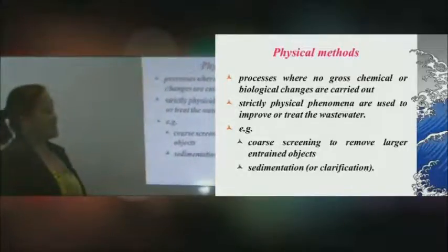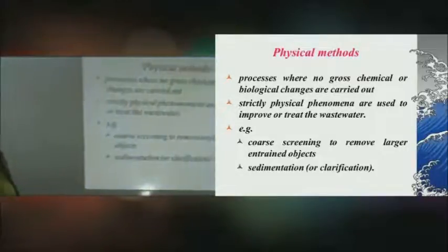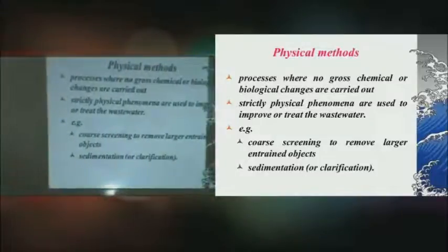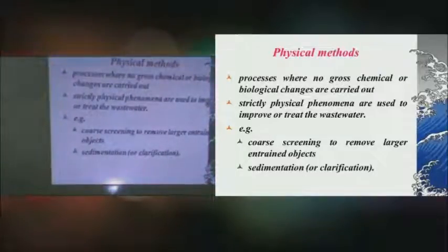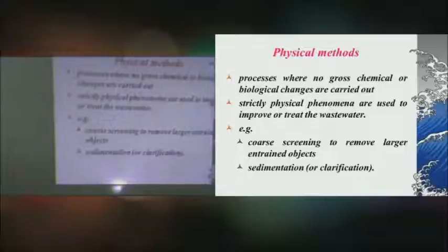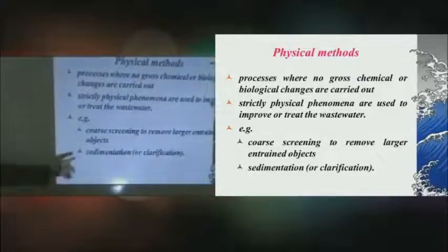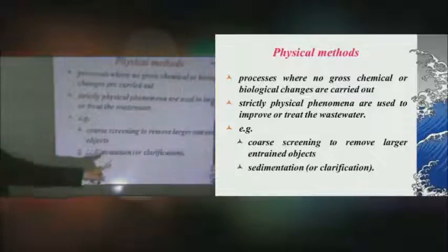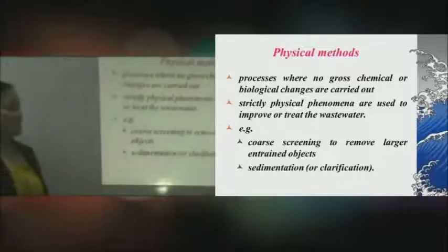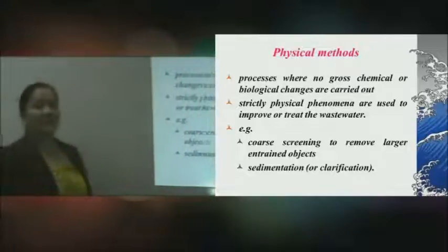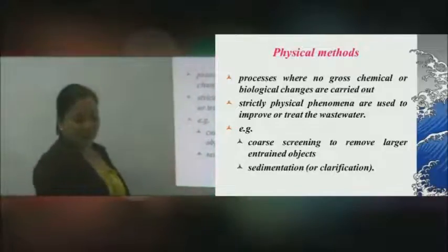So strictly physical phenomena, therefore this would refer to your unit operations. Examples would be screening to remove larger entrained objects, and sedimentation, normally utilized for water treatment, but for wastewater or sewage treatment plants, we use clarifiers or clarification.